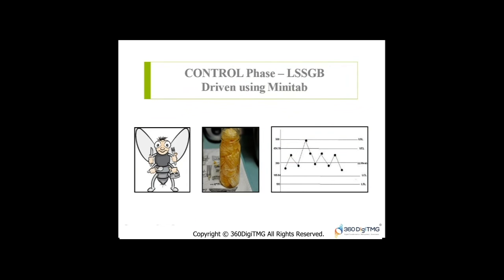That is fine, but what are these numbers? Control limits. Control limits are statistically calculated based on the data points that you enter. These are the data points that you enter. Let us go back to the cricket ball example now and understand the control limits. We know that the upper specification limit for manufacturing the cricket ball is 229 mm and the lower specification limit is 224 mm, right? These are the specification limits given to me by my customer.